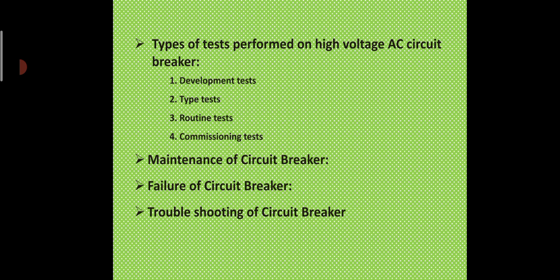Second one is increased resistance across the pole terminals. Its possible causes: reduced contact pressures, loose screw or bolt of the flange, contact surface might have worn out due to frequent operations, less wipe of the contact, depositions of oxidation on the terminal. And its remedial measures are: dismantle, clean and join, replace the contacts if necessary.